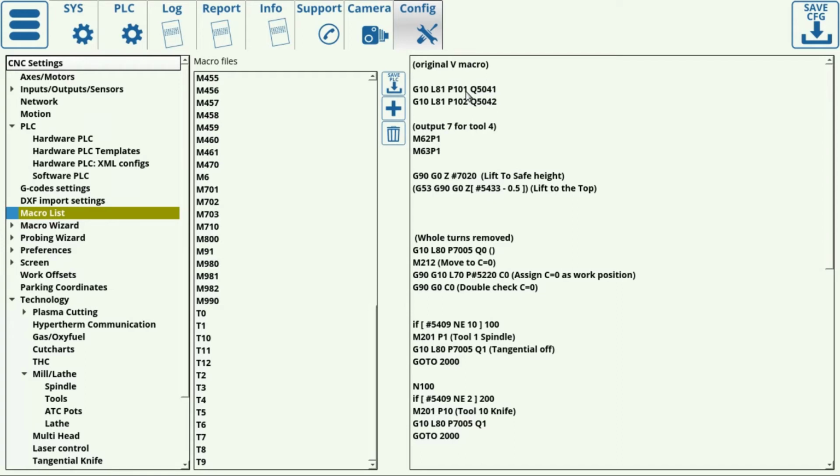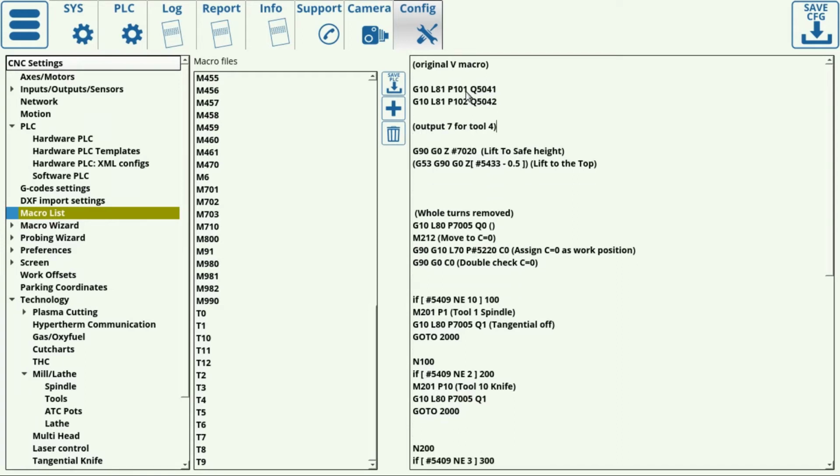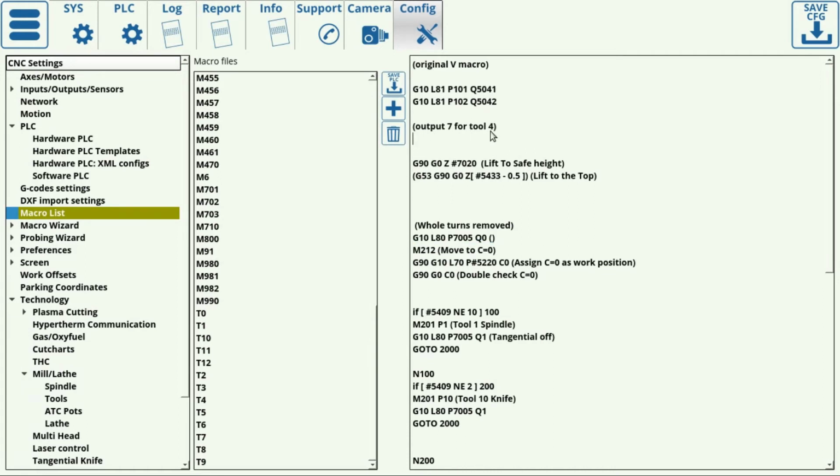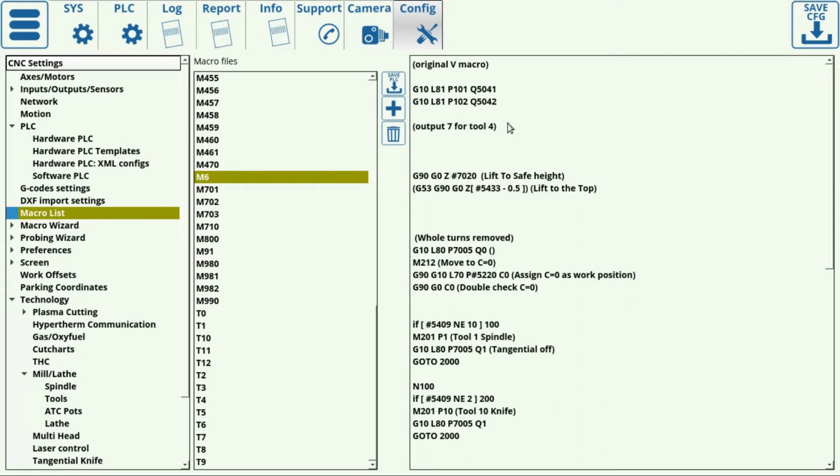Here, again, it is clearly seen that we can summon or run PLC commands from within our macro. So we can embed a certain PLC command and run it from within our M6. It is not the other way around. You cannot do it in the opposite manner where you summon a macro command from a PLC. So macro commands have that unique and very useful advantage here.